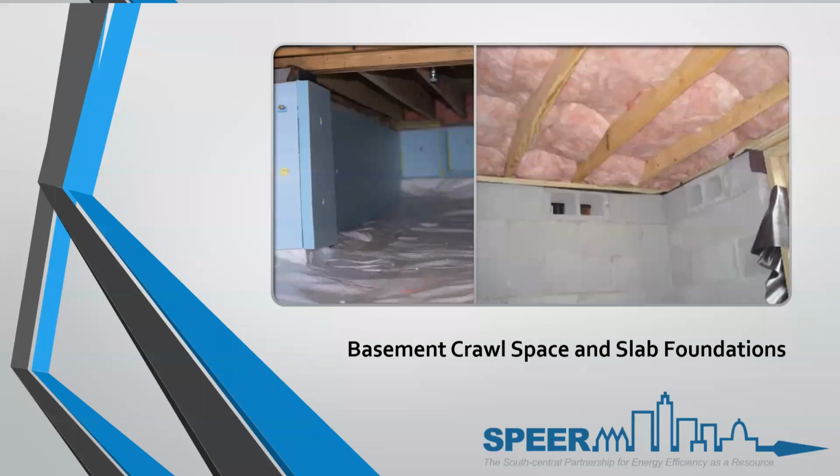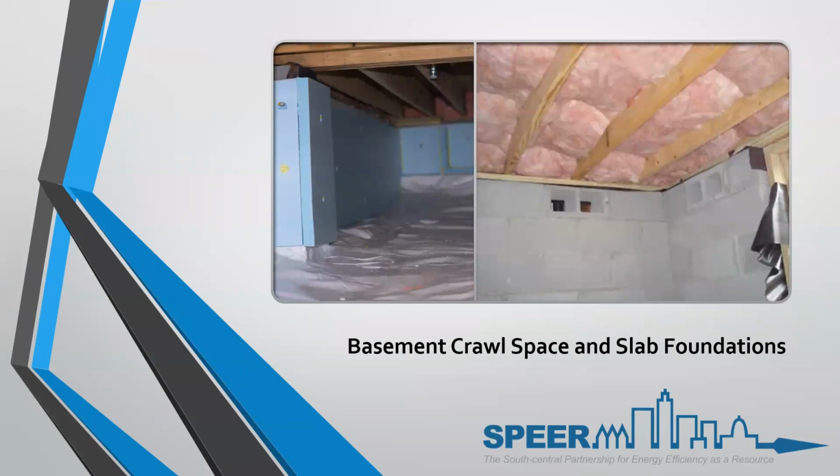So you can use a combination of both of those. With this, it just kind of shows crawl space insulation being placed under the floor or on the crawl space walls. If installed in the walls, it must not be a vented crawl space. And the floor covering, the ground floor, the exposed dirt. If it's concrete, then you don't have to do anything if it's concreted in.